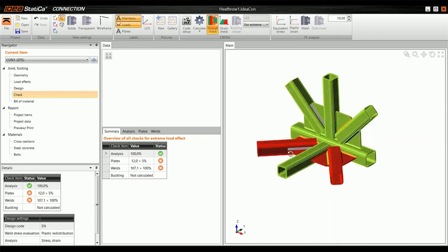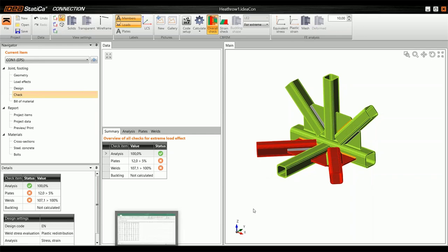But what's the trick here? This is calculated based on envelope forces. And this is, let's say, the old style, how we could call it. But the better and the right way is to check the joint with all the combinations.